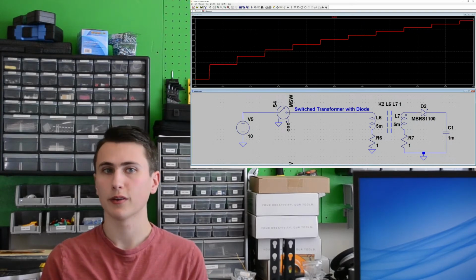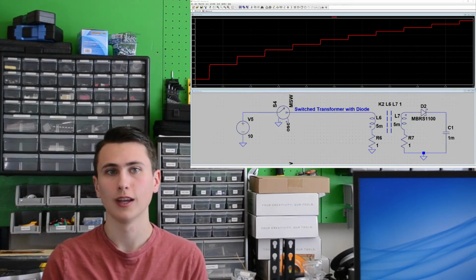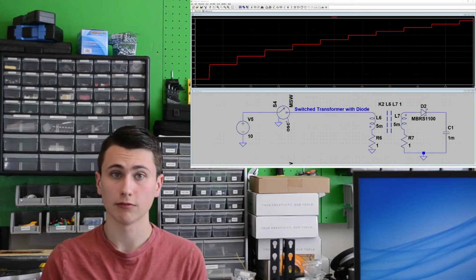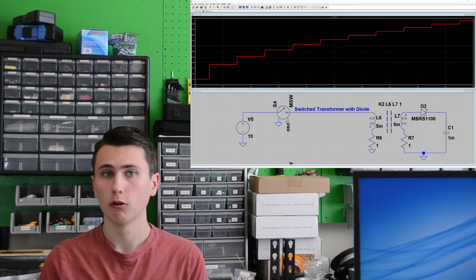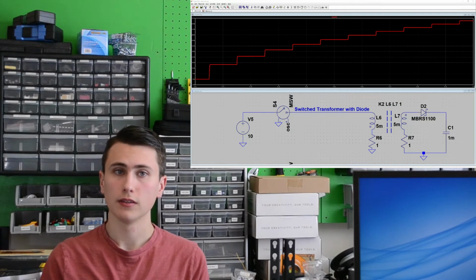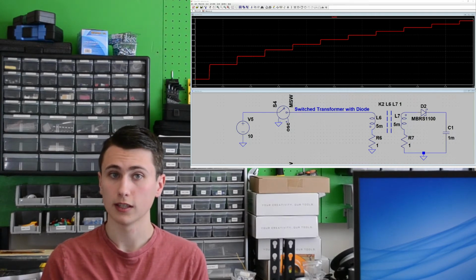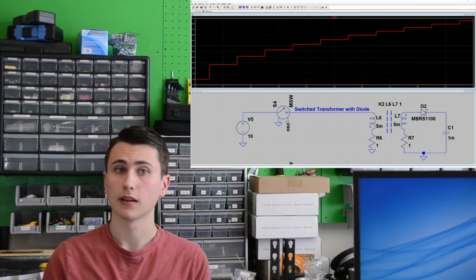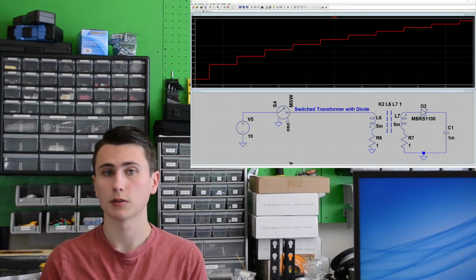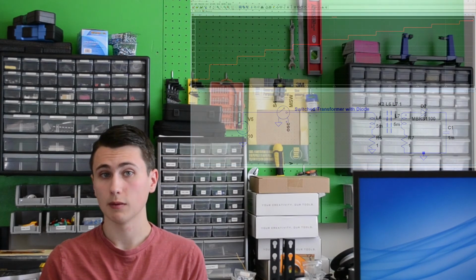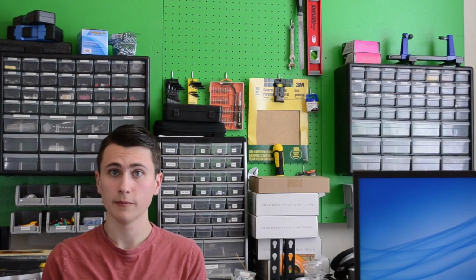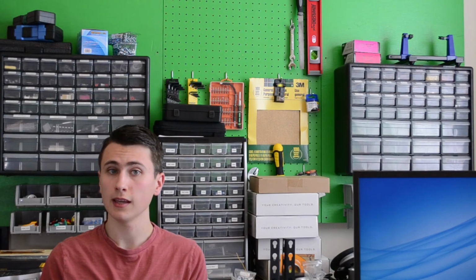This is the basic theory of operation behind a flyback converter. A flyback converter is a very specific flavor of switch mode power supply. When making a switch mode power supply, the switching frequency is much higher than what we're using here, and this allows the inductor and capacitor to be much smaller. That said, the same principles still apply. In fact, almost every topology of switch mode power supply depends on the ability of an inductor to store energy and then release that energy later by producing a voltage which attempts to keep current flowing in the same direction.